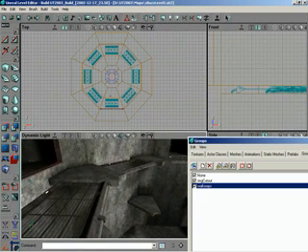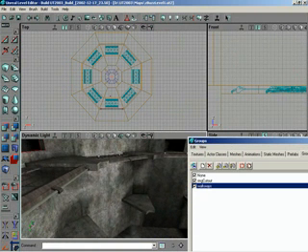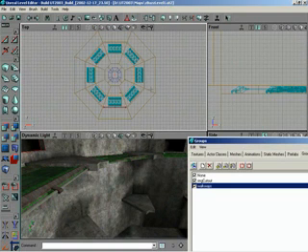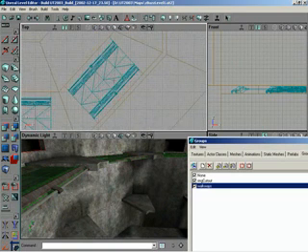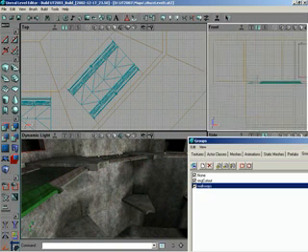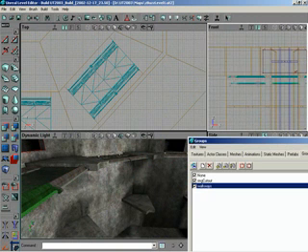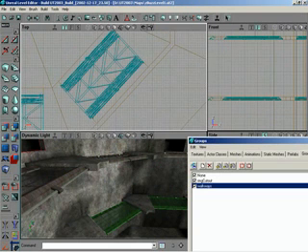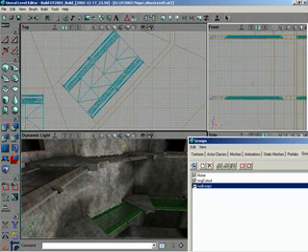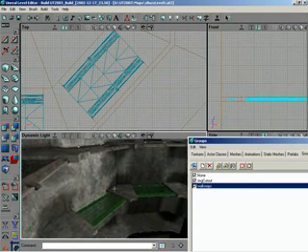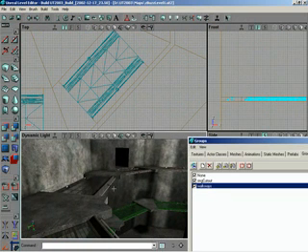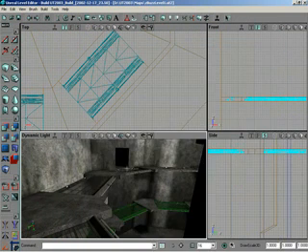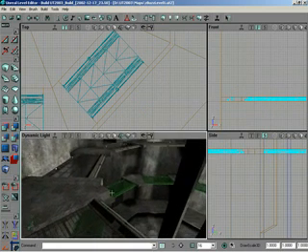So now we need those same 8 on that lower ring, so we can go back to our group browser one last time, select all 8, Control W to duplicate, and make sure that they center up again. And then from front view, I'll just Control drag them straight down. And if they line up, yeah, I moved them a little, so center them. Centered, centered, and there we have walkways for both levels. Very nice. I'll go ahead and close out the groups browser. Okay, so that takes care of our inner circular walkways.